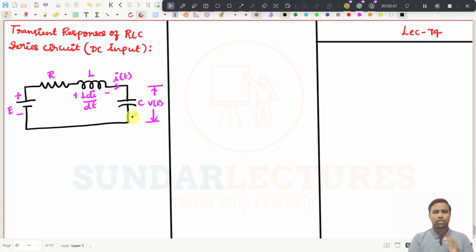Now what we are going to get is an expression for V of t, and then it is very easy to get the expression for I of t. What is I of t? Since this is a series circuit, I of t will obviously be equal to C into dV divided by dt. That we know, right? If current enters from plus to minus in a capacitor, then the current through the capacitor will be C into dV by dt.